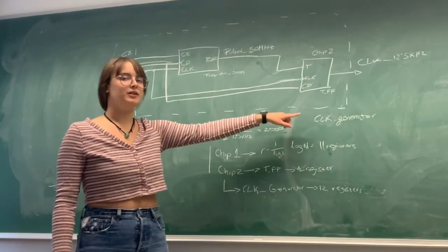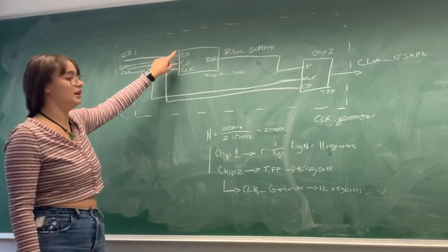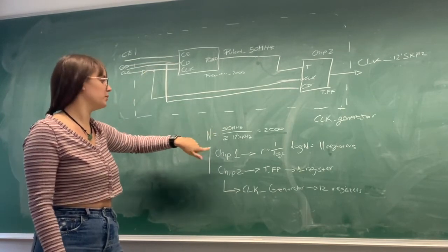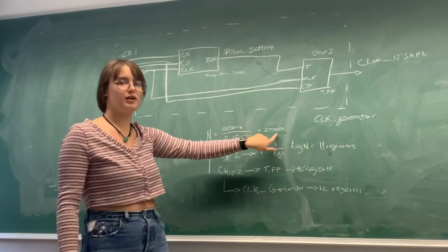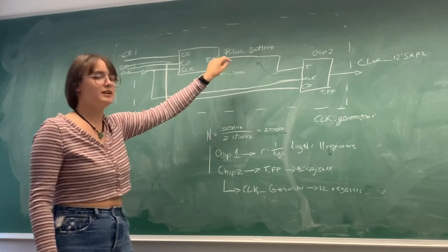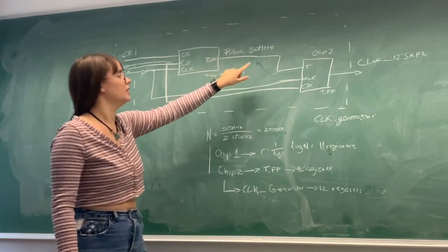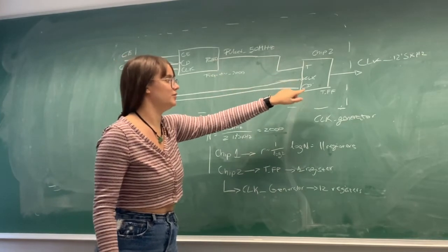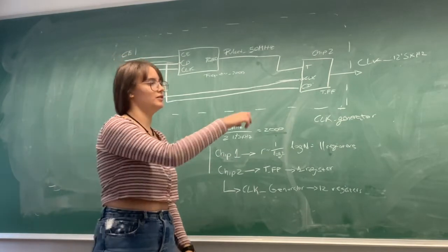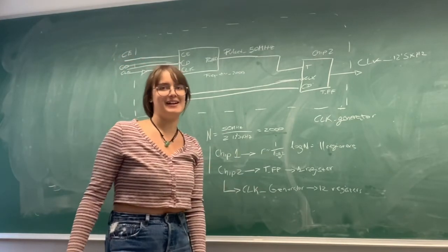So now I'm going to explain the clock generator, which has as inputs the count enable, the clear direct, and the clock. This clock is 15 MHz, and with this formula we get the 2000, that is TC2000, and the output we get here is 25 kHz. When it gets to the T flip-flop, we get the desired clock, that is 12.5 kHz.